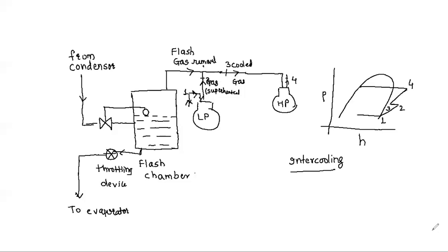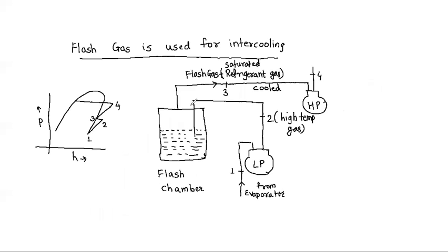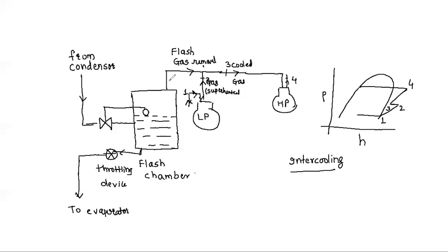One, as I said, that we can bubble this straightaway into the flash chamber, and the other is, as we have seen now, that we would have an external mixing of the flash gases. Now, how have these flash gases been removed? These flash gases have been removed because of the refrigerant which is expanded in expansion valve 1 up to the flash gas chamber pressure.